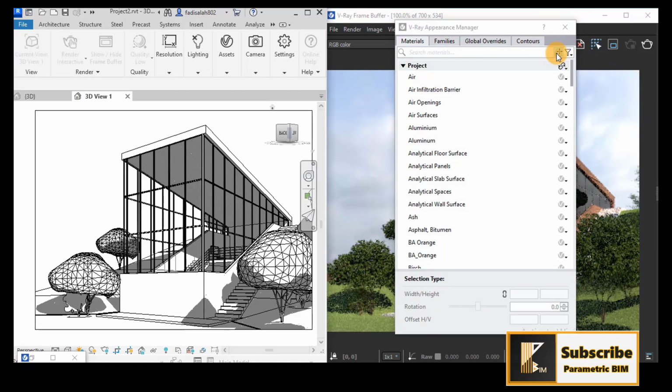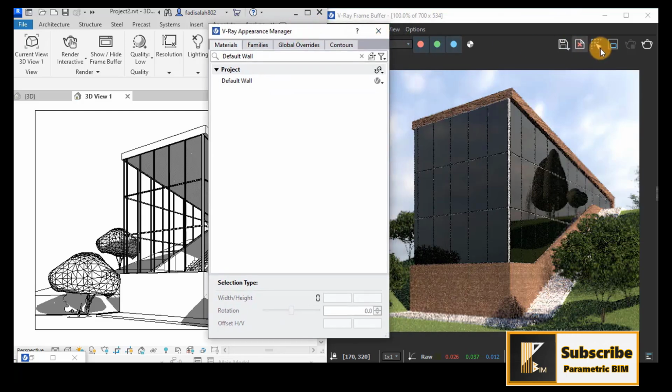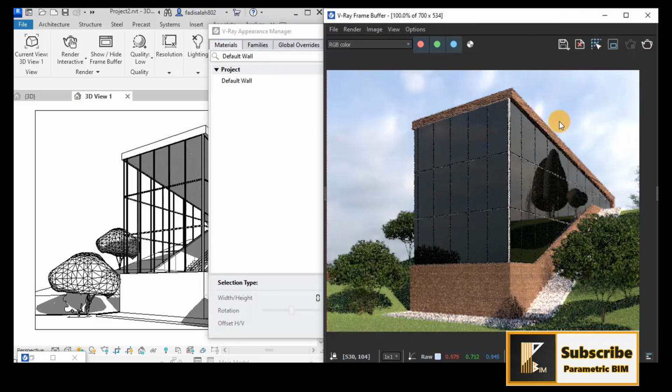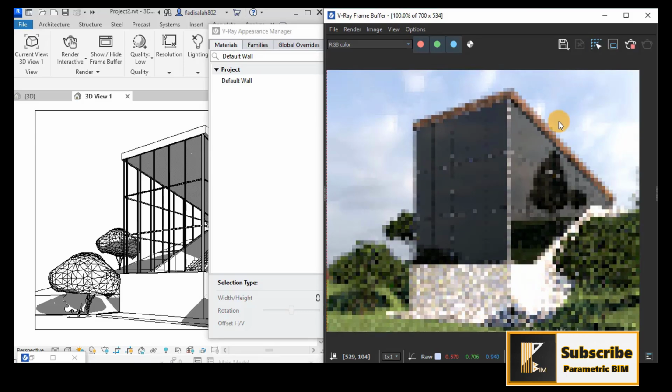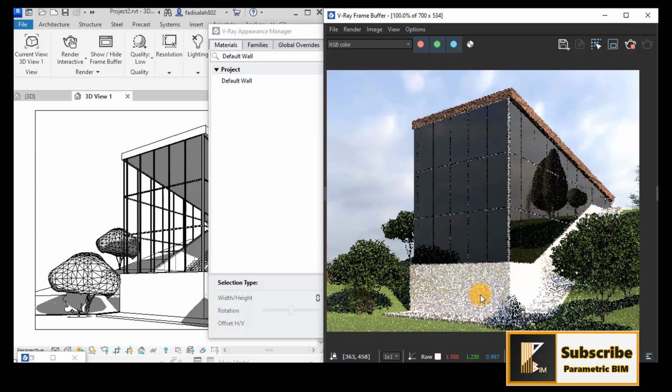So if I click here and go to the Revit, it will give me that this is the default wall and this material is the V-Ray material. If I delete it, as you see here, and render that, you can see now that it will return back to Revit material, and then we can change it to another material. So this is the default material in Revit, which is maybe gypsum board or something like that.